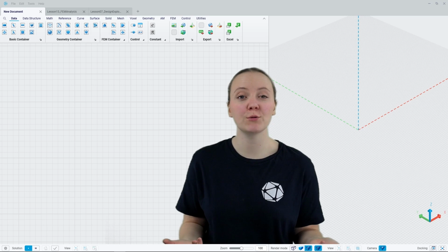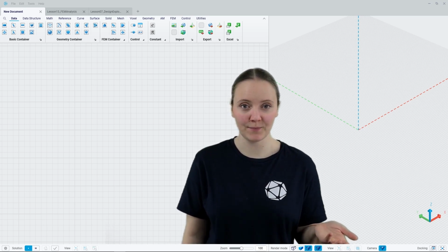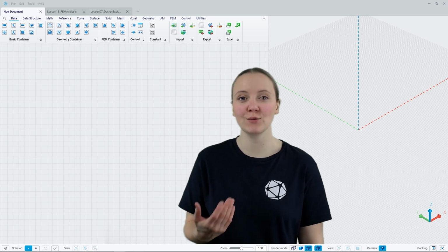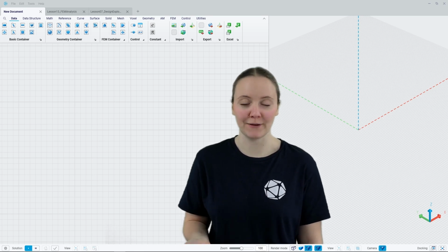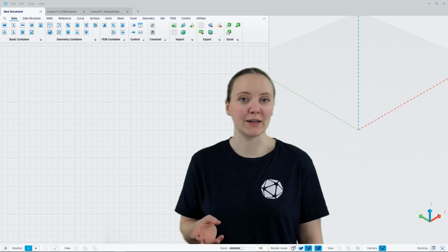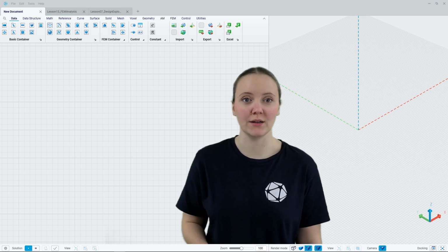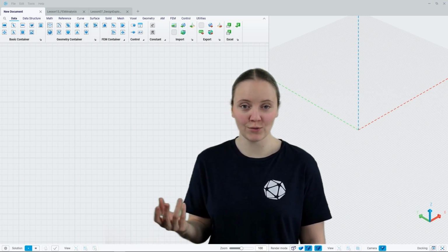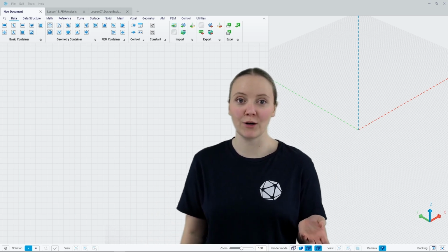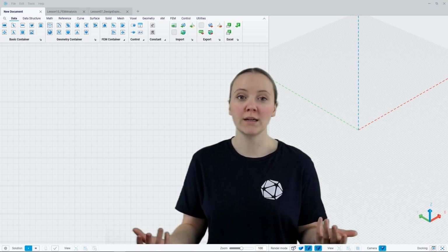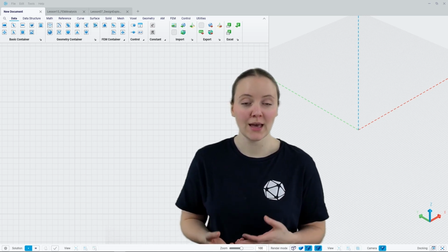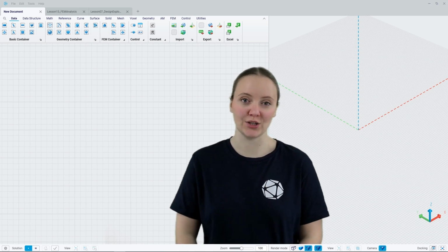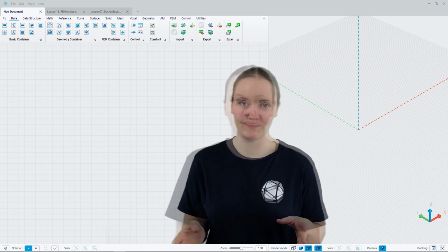So first, you will create a parametric CAD design. Then you will parametrically extract reference geometries and use them for an automated FEM analysis. This FEM analysis is used to evaluate the displacement in the design, and with this evaluation value and the different parameters for our parametric CAD design, we can now do a design of experiment and choose which design is best based on our simulation results fully automatically.